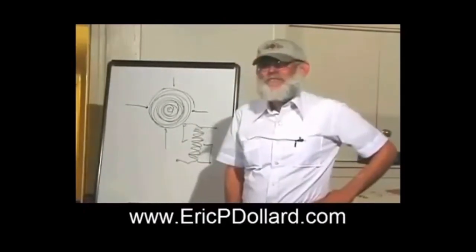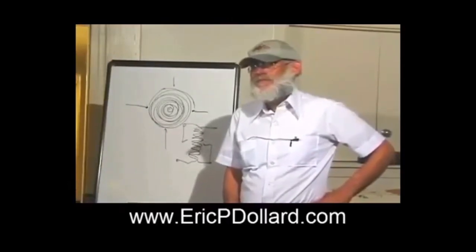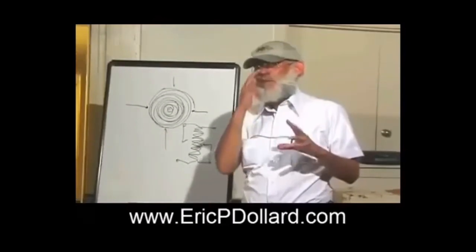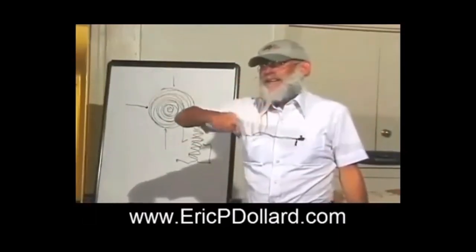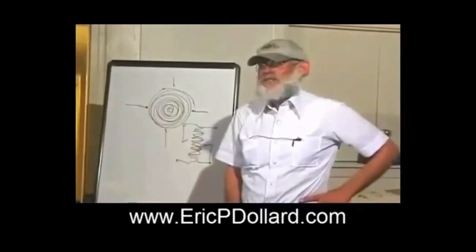Speaking of experiment, you flailed a cord or something through a magnetic field and counted different speeds. No, what I did is I took a relay coil, which had about 1,000 turns of wire in it, so it could absorb up the magnetism to the point where it would drive the headphones. It had a magnetron magnet. I took the coil and moved it around the magnet, and I could hear the magnetic field scraping through the coil. There would be a scratching noise.